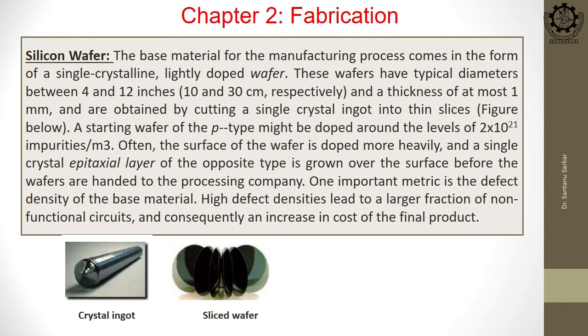So, I hope you all know the basics, we have a silicon crystal, which is known as the ingot. You know how this crystal ingot is formed. So, we have molten silicon, and then one crystal is dipped and slowly touched to the silicon liquid surface, and then it is slowly moved up.